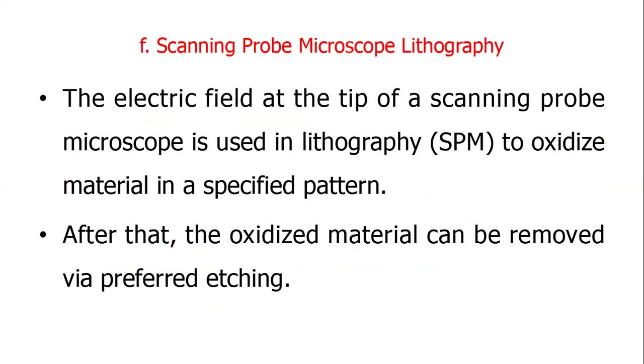Scanning probe microscope lithography. The electric field at the tip of the scanning probe microscope is used in lithography to oxidize materials in a specified pattern. After that, the oxidized pattern can be removed by a preferred etching.